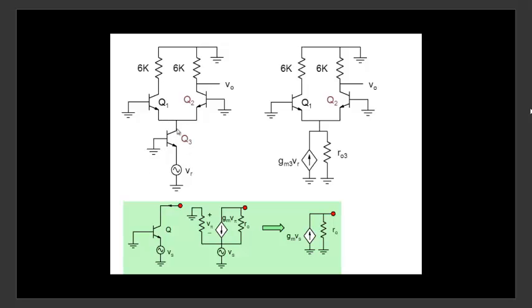See, what happens is a circuit can be broken into many blocks. Each block, if you take it and transform it into Norton's equivalent, what do you get? You get a current source and a resistor. So the whole block that you have simplifies into one current source and one resistor. Another block that you take and transform into Norton's equivalent becomes a current source and a resistor. So the circuit simplifies. Okay. So I'm left with this one. So I take this one here and I arrive at this one. Okay. GM VS here. Now what do I do?